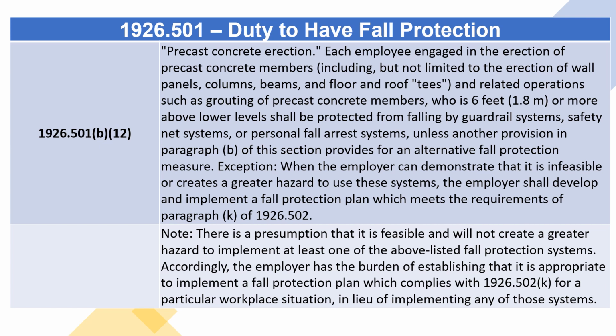Accordingly, the employer has the burden of establishing that it is appropriate to implement a fall protection plan which complies with 1926.502 K for a particular workplace situation, in lieu of implementing any of those systems.